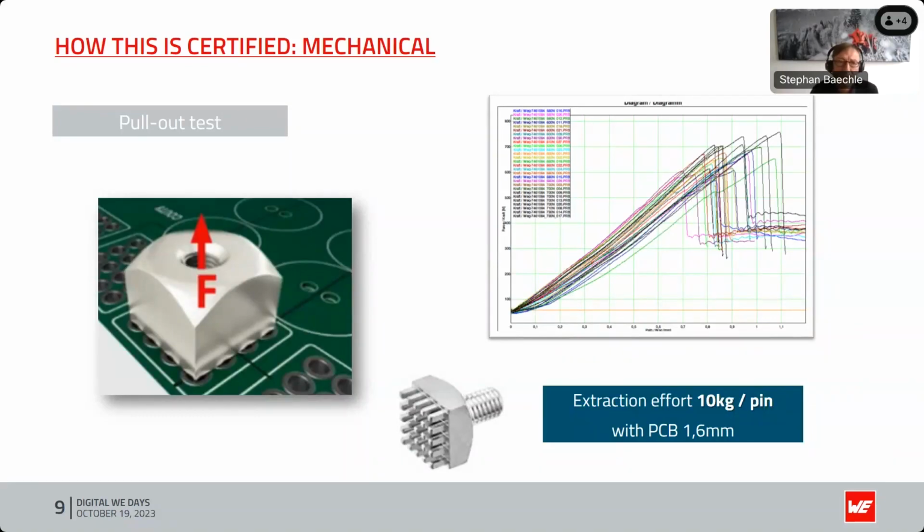The thickness of our PCB for the press fit technology can be between 1.6 millimeters and 3.2 millimeters. This is related to the pin length of our products. The pin length is 3.8 millimeters. And to control a proper press fit, you have to turn around your PCB and watch if the pin looks out of the PCB. And this leads to PCB thicknesses between 1.6 and 3.2 millimeters.